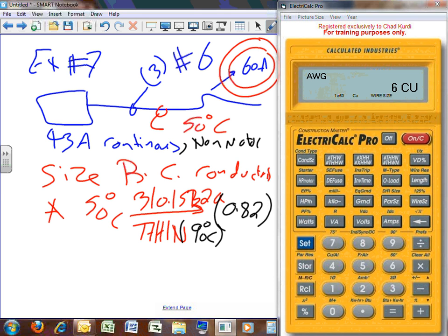You have to go to 310. They moved it away in 2011. It's 310.10 something. It will tell you that the insulation is rated for 90 degrees or so. Where am I here, Chad? 310.104. Thank you. 310.104, table 310.104(A). That's a table which tells you that's 90 degrees. Okay. Now, any question about this?